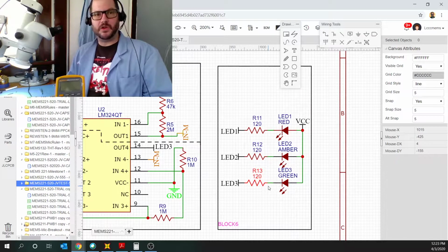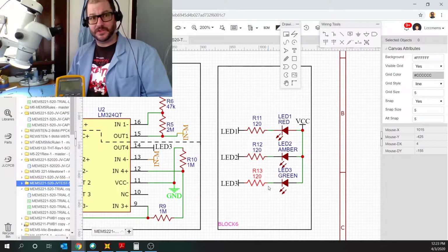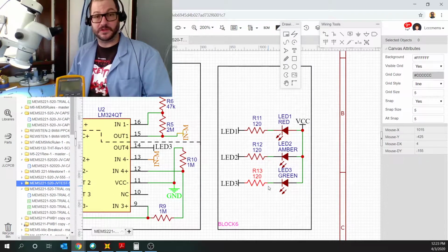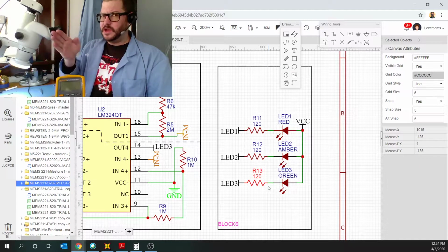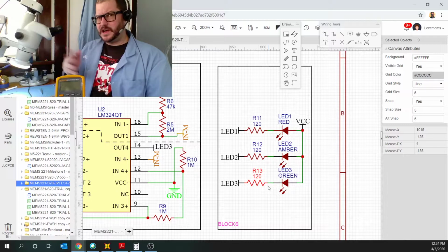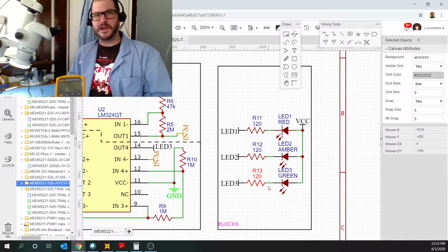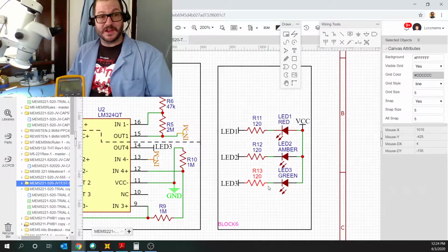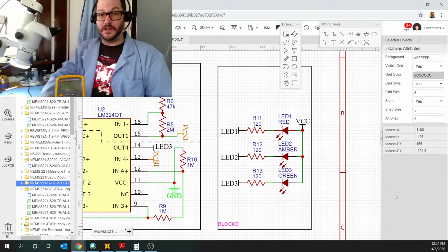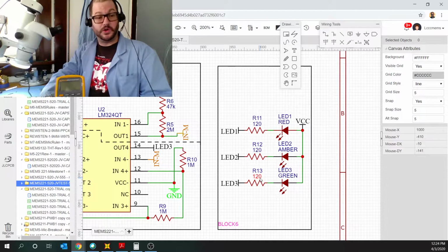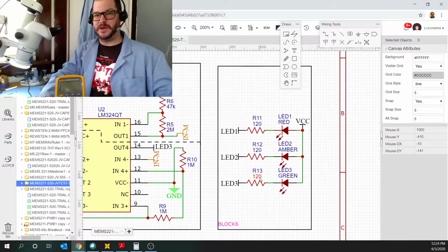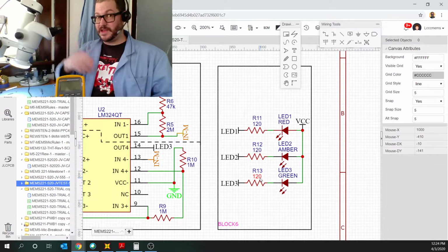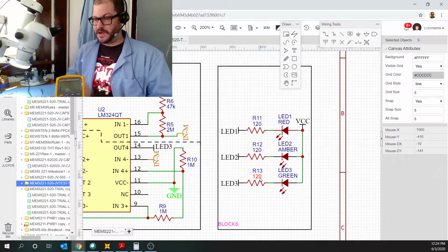So the only way that I have a control value in my circuit for that is the current limit resistor. The larger the resistance happens to be, the more that blocks some of the current. So basically, the smaller the value of resistance, the brighter the LED is going to be when it turns on. Now, I don't want to just have that set at nothing, because if R11, R12, and R13 were 0 ohms, they were just what we call short circuits, that may potentially be a large enough amount of current that would actually just fry the LED outright, which I don't want.